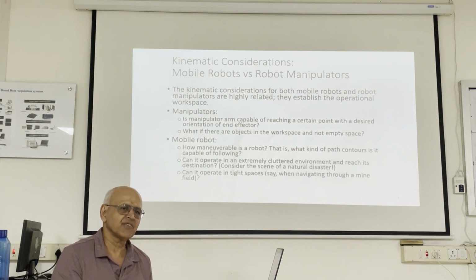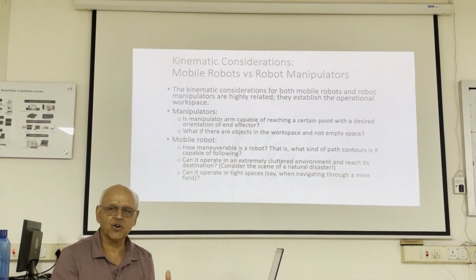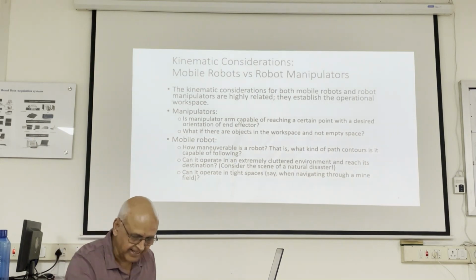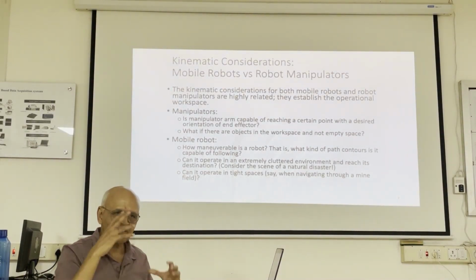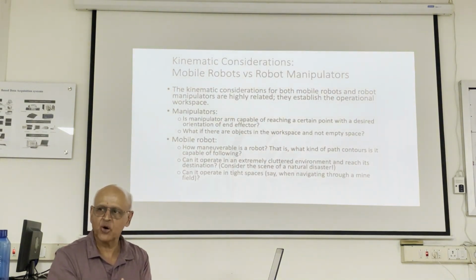On the other hand, for a mobile robot, you're moving all the time. So localization is very important. Now, one of the mistakes we make is we view localization through the eyes of a human being. So when we walk down the hall, we don't need to precisely localize. It doesn't matter that we hit the same tile every single time when we are leaving class, because we have other things going on in our head that helps us to overcome that.